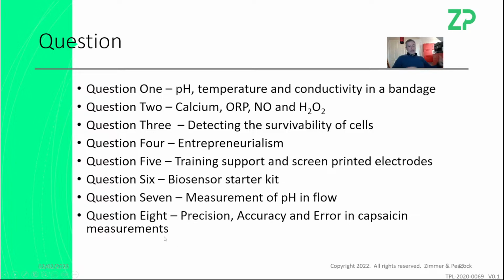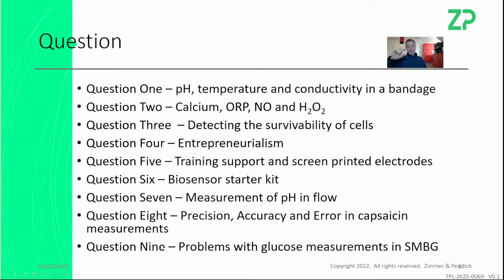Precision, accuracy, and error. HPLC certificates of analysis, they're interesting and they're useful and they're indicative, but they're actually not necessarily as accurate or even precise as you would like to believe. And if there's an offset between, for example, the food sensor and an HPLC, you can adjust for it. In the food industry, quality control is really more about reproducibility. If the HPLC is telling you that the thing is 63,000, we're telling you it's 97,000, put in a response factor of 0.65 and they'll line up. I just don't believe they're necessarily accurate, but you need to show consistency, so that would be one way of solving it.